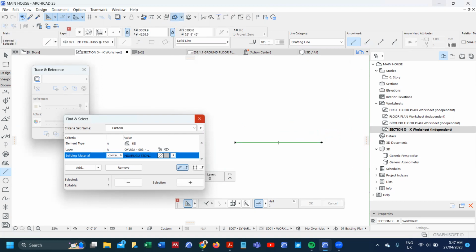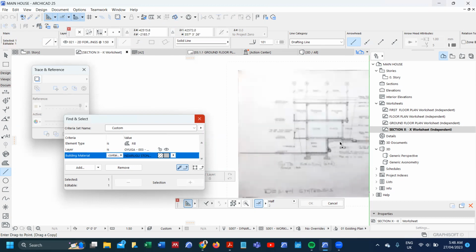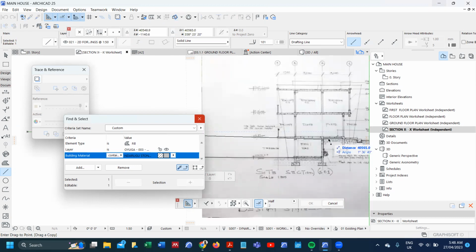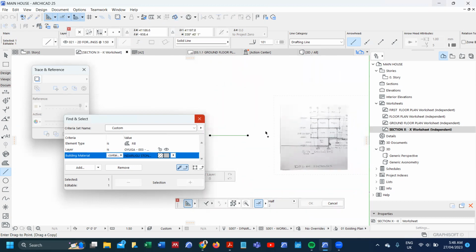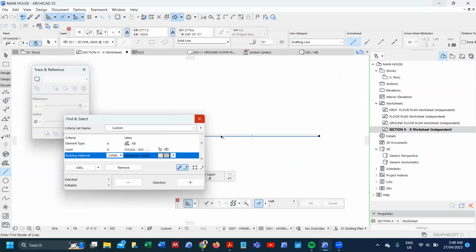so I'm going to use a drafting line, okay, to quickly pick up this. Our ground floor slab, I think in this case is suspended. It's a hybrid of a suspended and a ground. So allow me to work with around 200, and then I'll place it maybe 100 above the ground. I believe you know how you place it 100 above the ground.